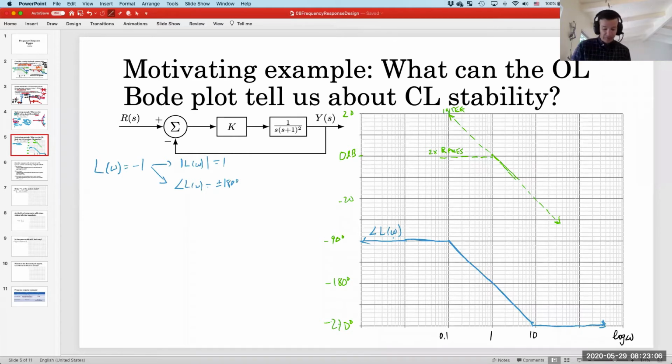Okay, so let's now try to combine the magnitude curves. And I want to start with setting k equal to exactly 1. All right. So if k is exactly 1, it contributes 0 dBs of addition or subtraction, which means that all I have to do is add the green curves that I have, and I'll be done. So let's overlay this.